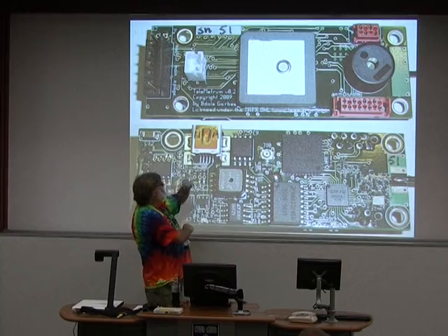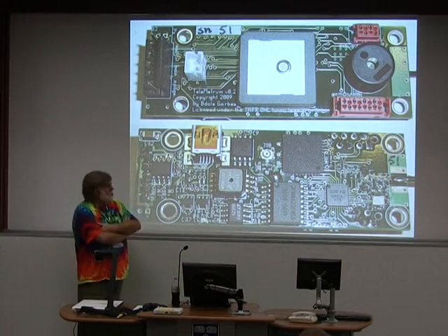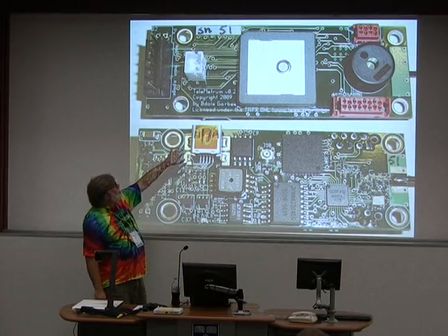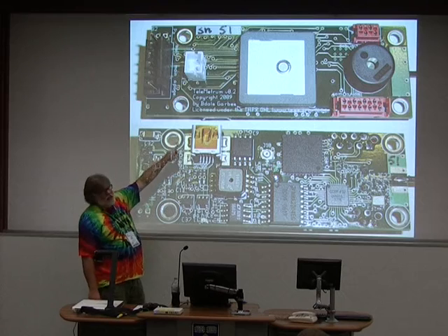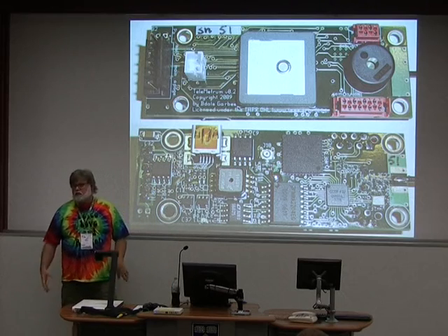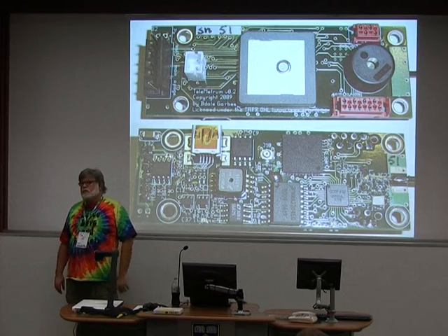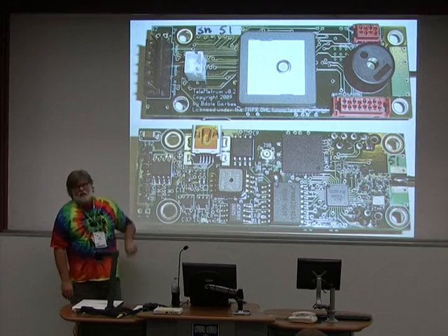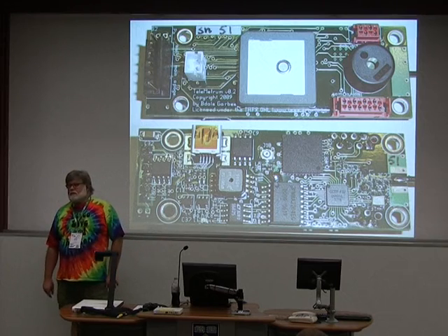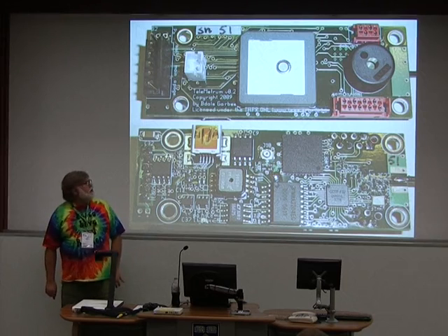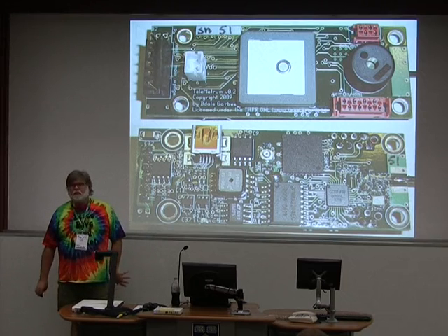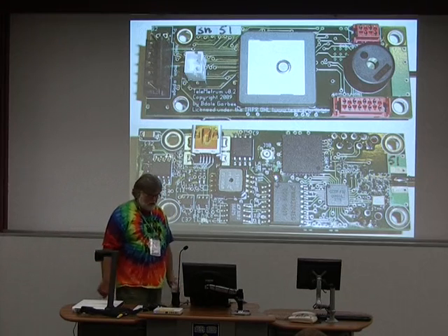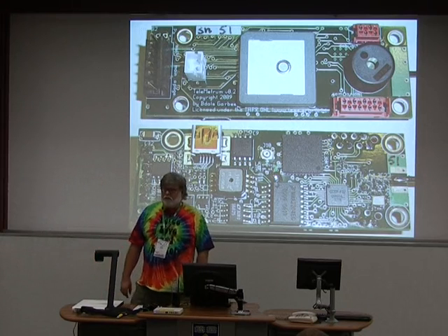There were problems with this, though. That's a passive GPS patch antenna, and it turns out that for a bunch of reasons I won't go into right now, but because you guys like RF, I'll tell you the big one. That patch assumes that it's on a 50 millimeter square ground plane or larger. That board's 25 millimeters wide. The consequence of that, if you know anything about patch antennas, is that patch is actually several megahertz detuned from where it should be. And so the GPS performance on this board just sucked, by which I mean time to first fix. When you turn the board on, how long it took to figure out where it was was really long, on the order of many minutes.